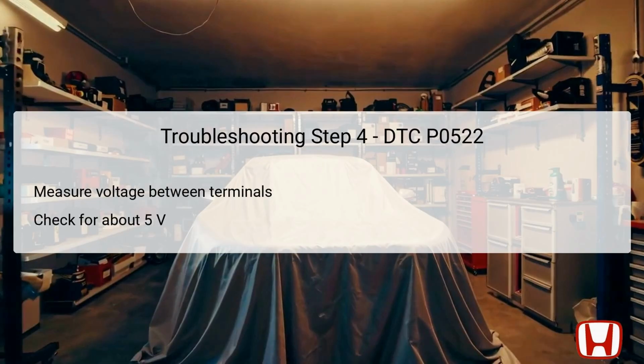The critical condition to check is whether the voltage reads about 5 volts, which is the expected operational voltage for the system. If the voltage is indeed around 5 volts, it indicates that the EOP sensor is likely functioning and the problem lies elsewhere down the line. Conversely, if the reading is lower, it points toward an issue within the electrical circuit, requiring a deeper investigation into